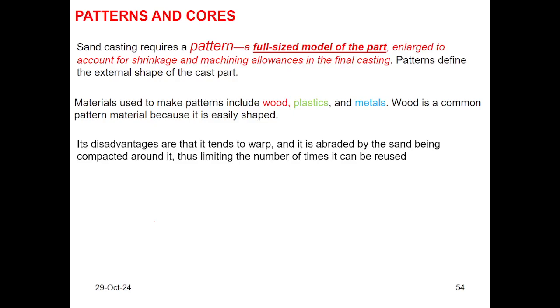Patterns are, in most cases, made of wood. But wood is not a strong material, so wooden patterns can be used only a few times. If the pattern is made of metal, then it can be used n times. But metal patterns are more expensive, because metal patterns are prepared beforehand through a casting process.